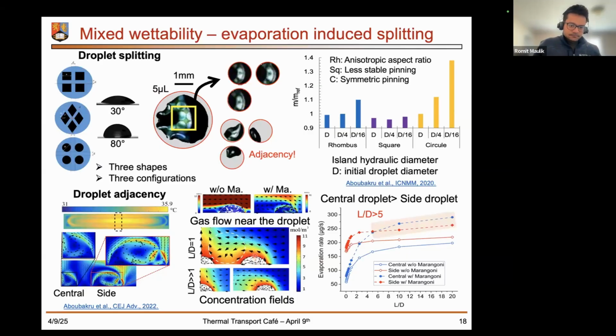So for the interface, at first we had an assumption of no tangential velocity or tangential transport. In the absence of a slip boundary condition, the velocity of the liquid at the interface at the bottom is equal to that at the top, and this solves the gaseous phase, and then it provides the amount of m dot that is evaporating from the droplet, and then it's translated to the velocity.